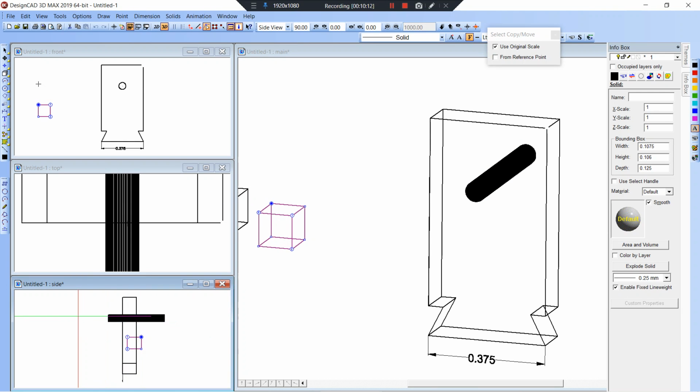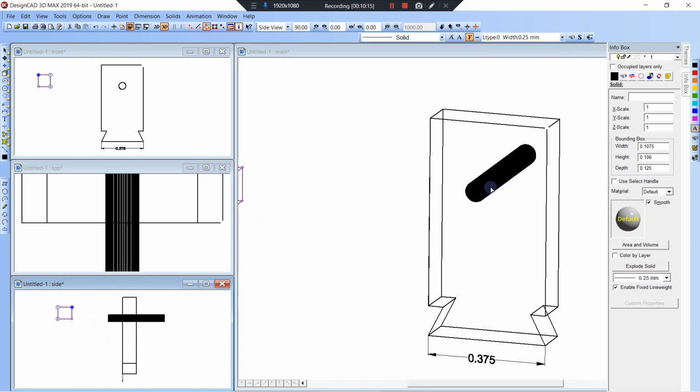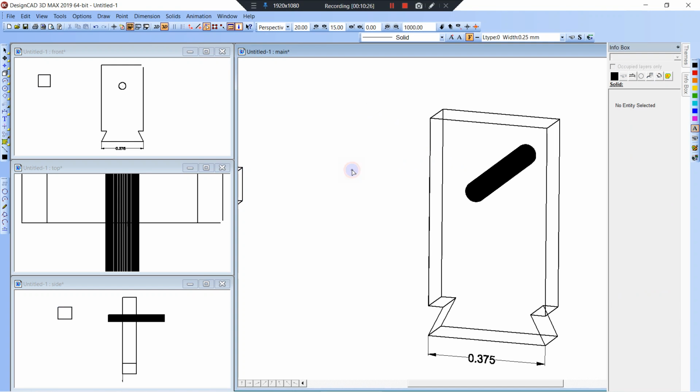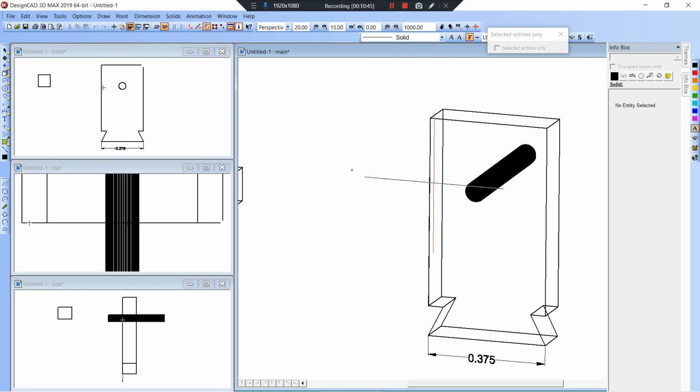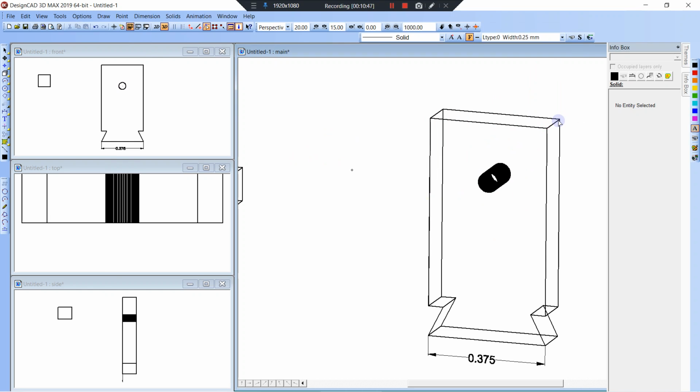and that's creating, now you can see that that's going through there. That cube is in the background. So what we can do with this is we can extrude or subtract that. So let's do that. Draw. What am I trying to do? Extrude. So let's go Control J, I think. No, I forgot. Draw, solid. Yeah, solid, subtract. Control U. Yeah, Control U. We're going to subtract this from that. Enter, and then we just end up with the hole through there. So now it's a solid with a hole in it.